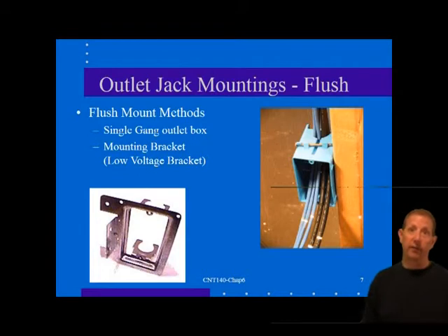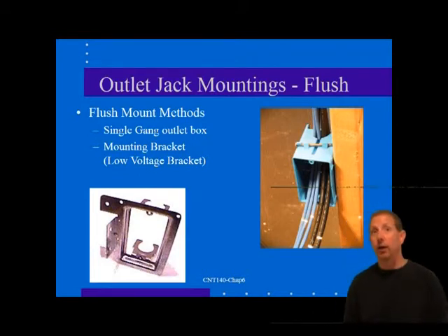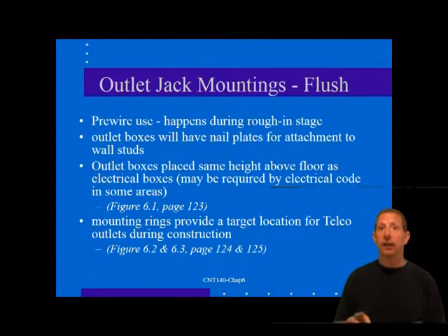The 2-inch wide box is the most common for this style of wiring, although a 4-inch square box with a 2-inch wide mounting ring may also be used. In general, the telecommunications outlet plates that mount to these boxes are designed for the 2-inch opening. The opening sizes are also referred to as 1 gang or 2 gang boxes. And that's how we look at them in the trades.